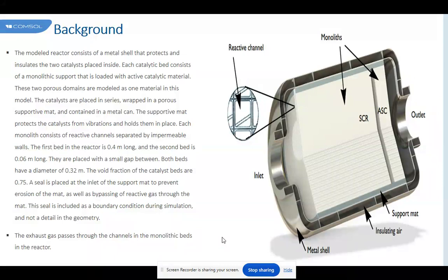However, according to this simulation, the computed fluid has a strong preference for the zone with the lowest cell count regardless of the temperature. Despite the cell density of the ring monolith, the two cases with the 900 per 2.5 monolith in the core show higher temperatures than those with a core of 400 per 6.5. The thermal conductivity of the 400 per 6.5 substrate is approximately 30% higher than that of the 900 per 2.5 substrate. Hence, a more homogeneous temperature would be expected in that region.